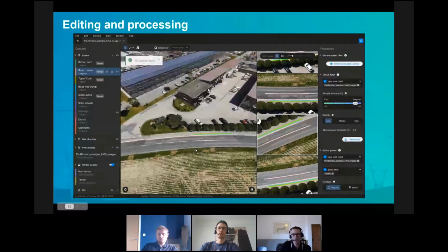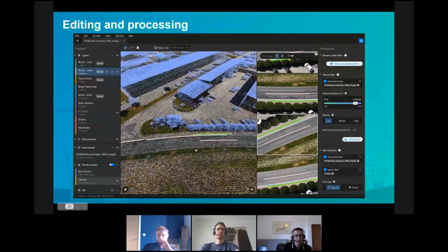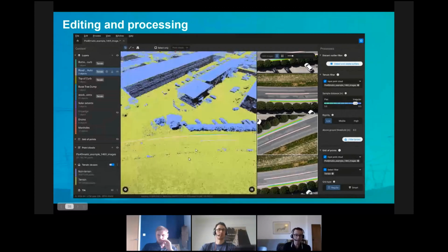And then after that, that's some of the manual stuff. I went through, looked for any noise, didn't find much in the project. From there, it's that first binary filter of whether or not to, or how to classify the ground and non-ground. You can see here I'm setting an above ground threshold of about 20 centimeters, so pretty close. It's definitely not nearly as detailed as you'll find in a full classification kind of a tool, but so often this kind of a result that you see here is all that we really care about. Is it ground?